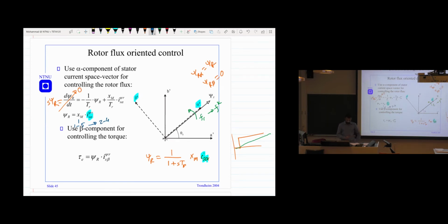So, for example, if you want to get the CR like 0.9, we say that when we keep the rotor flux constant, we try to keep it 0.9 or maybe 0.92, not more than that. Because if we have it more, then stator flux becomes very high and the machine can be saturated. So we don't want that. So therefore we keep it something like that.